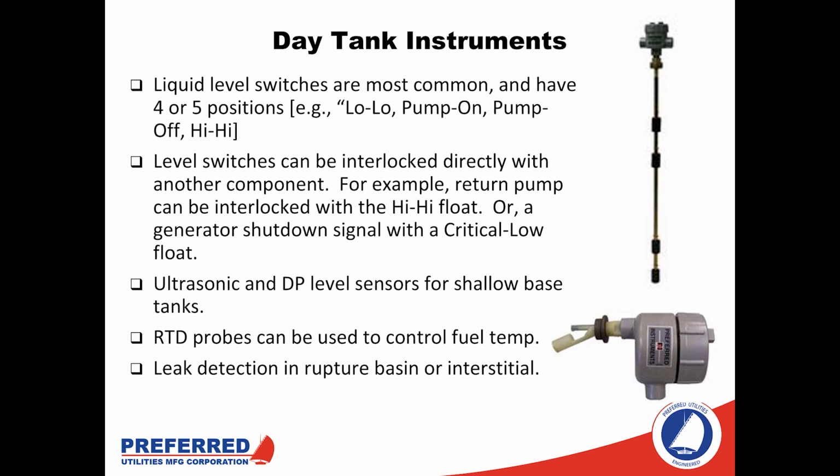Now, in an advanced system where the customer also wants to know the exact number of gallons that is stored not only in the main tank but also in the day tanks, we can provide a backup analog sensor to work in conjunction that will just indicate the actual volume of fuel that is in the day tanks. Some other devices that you would see on there are leak detectors as well as RTD probes, as the temperature of the fuel in the day tank is something that's becoming more critical, as we talked about before with generators returning hot fuel, or here in the Northeast with fuel getting cold as well. So being able to tell what the temperature is at each part of the system can be important also.